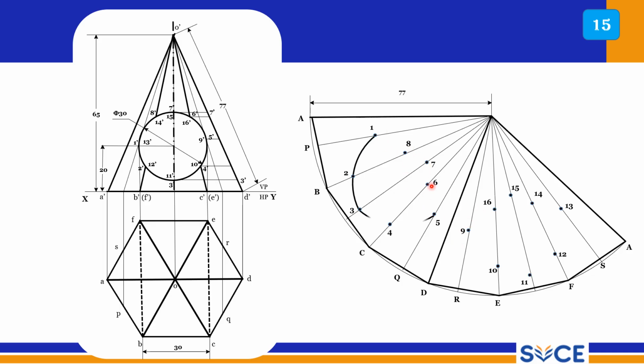So this is how you should connect them, and similarly this side you connect them, and draw the thick lines for these edges, right? C2 4 and 4 to O should be thick line, B2 to the A2 O should be thick line. Draw thick lines for the slant edges, right? So there ends your problem, right? That is problem number 15, a through hole drilled through this hexagonal pyramid.